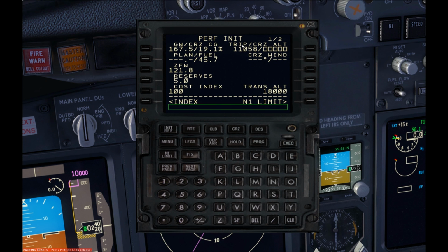Okay, so what it does then is calculate our best flight level, and that would be 11,580 feet for us. But we already have a predefined cruise altitude. I've used 260 for today. So I then put 260, which is a flight level, because above the transition level you don't use just 26,000 feet anymore, you use flight levels. So it's basically divided by 100, I believe. Okay, so we just line select that in. It would say on the enable cruise altitude, but that's okay for me because I'm not actually doing the flight. I would correct this if I was. I'm just going to leave it out for now.